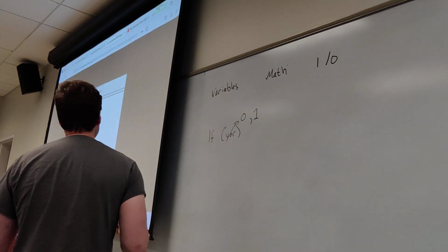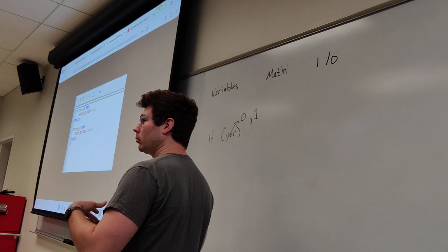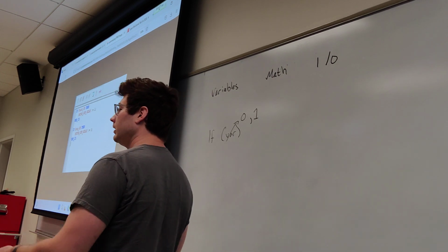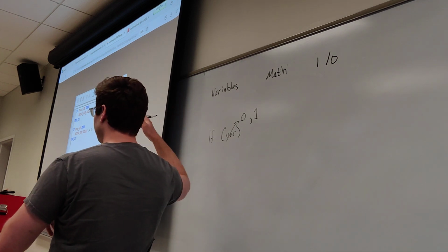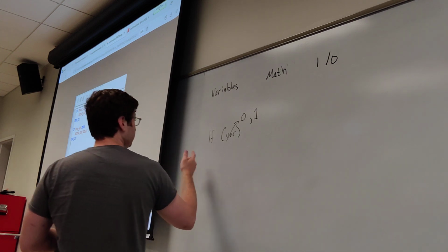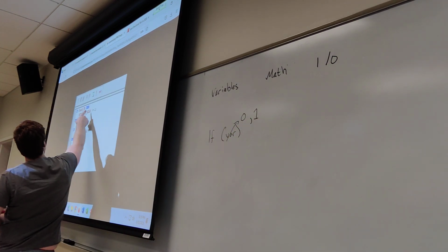So that variable could be manually written to it, like we said that somewhere in our program, high or low, or something from the outside world might be setting that high or low in terms of an input, right? If like we have a level sensor, water in a tank, right, trips our sensor, now we're saying if that sensor is reporting a 1, then do this thing.